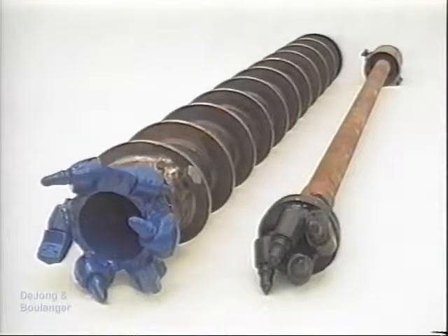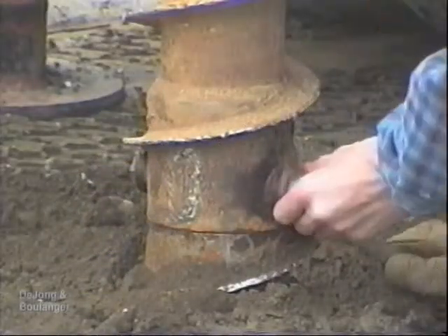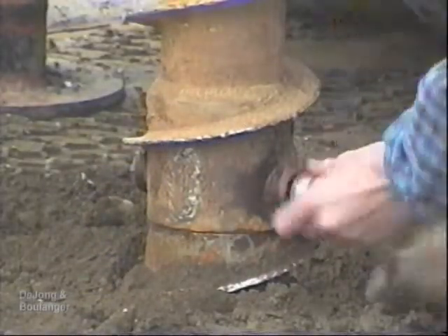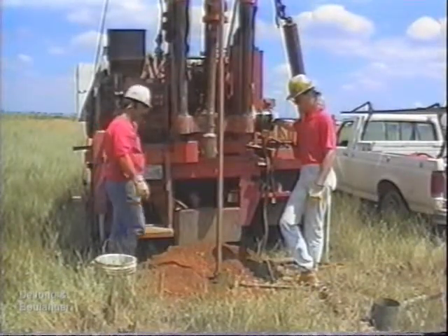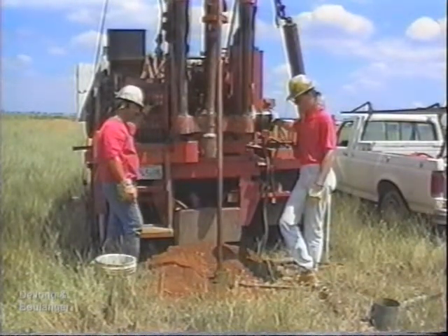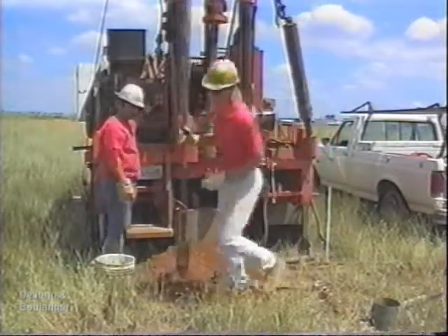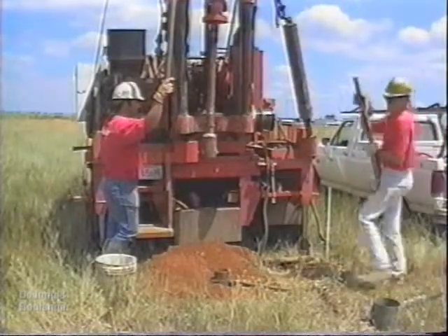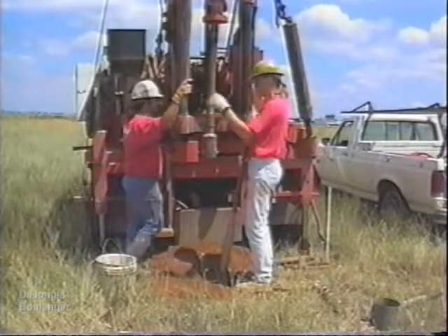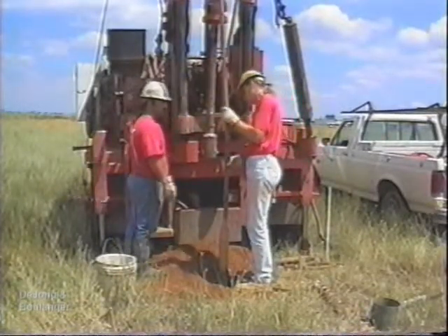The inner bit is connected to drill rods that run through the hollow stem, and the other bit is bolted to the bottom of the lead auger. While drilling, the inner and outer bits rotate together, cutting and loosening the soil at the bottom of the hole. The soil cuttings are carried upwards by the auger flights to the top of the hole. To sample, the drill rod to cap adapter is removed, and the drill rods in the center bit are withdrawn from the hole. A sampler is then connected to the bottom of the drill rods and lowered down the hole for sampling. After sampling, the center bit is reconnected to the drill rods, lowered back down the hole, and drilling is resumed.